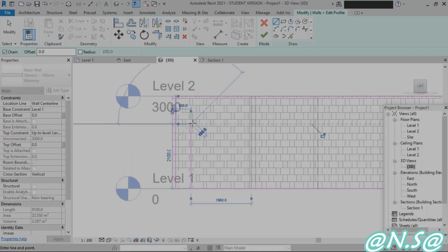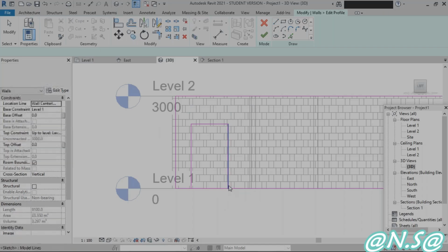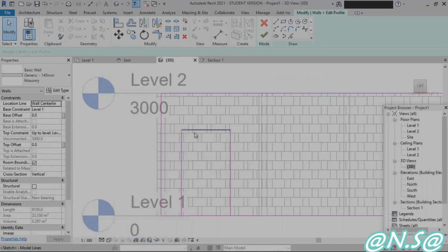Vertical height, one more click there, and the width I require is 1.2, nothing but 1200, enter. Next I'll come back to the bottom, so that I end it exactly at the horizontal line at the bottom boundary. So now this is a regular one.